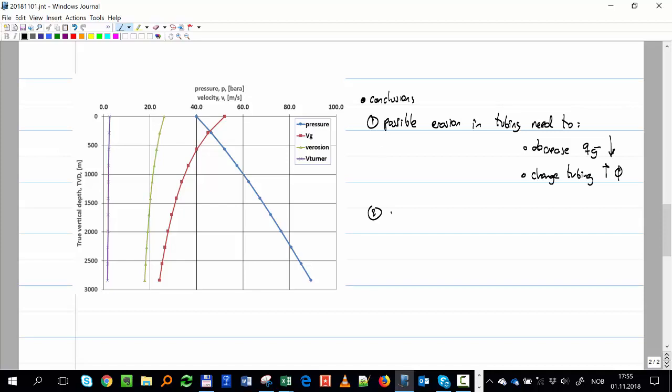And then the other conclusion, that's number one. Number two is no liquid loading expected. Which is something bad and that's something good. Liquid loading is this accumulation of the liquid in the well. You start having accumulation because you cannot empty the liquid from the well. So which outcome concludes that there will not be any liquid loading?